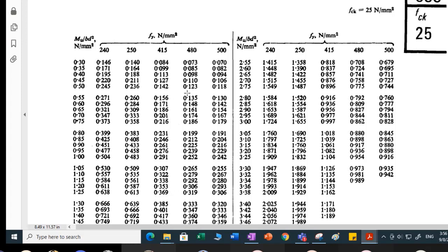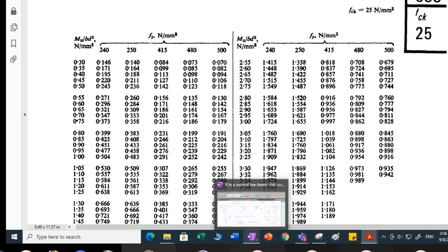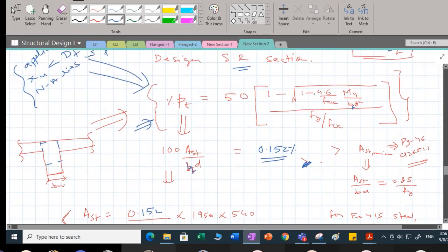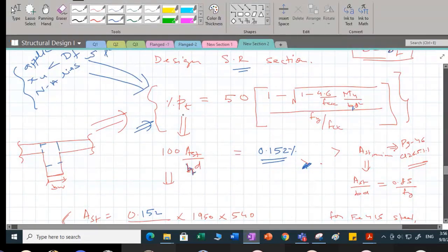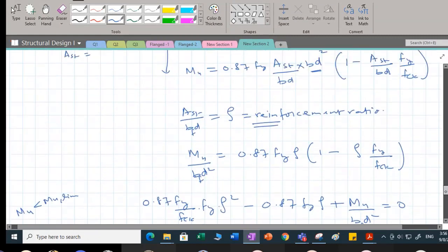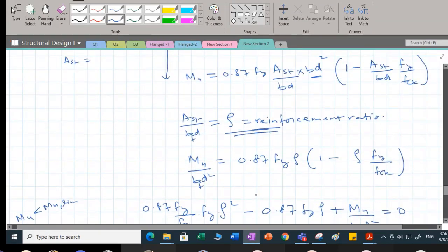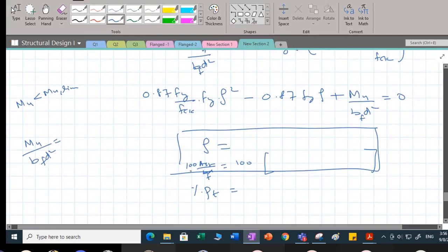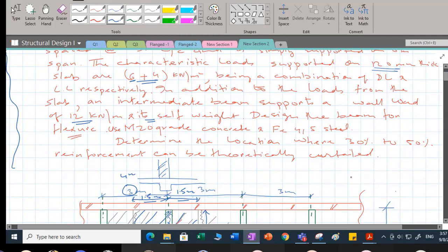And this percentage tension reinforcement is also very useful when you compute the shear strength of the concrete. So that is why I thought of introducing it. As I said, I have given you the basics of how it has come, by introducing this reinforcement ratio and modifying it by multiplying by 100, which I call the percentage tension reinforcement. Is this clear? Yes, sir. Okay. If there are any other questions I would like to clarify, else I'll move to the other part of this question. For the other part, I assume there is again no doubt.